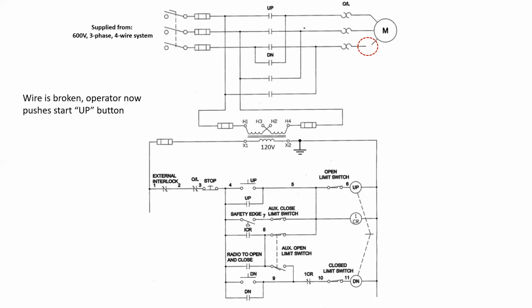So the wire's broken, and if we start the motor, it's highly likely that in this single phase condition, it will not have the torque available to get going and start. So what you might end up hearing is the motor trying to start, but due to the load on the shaft is unable to, and it will hum. It will hum and it might turn a little bit, and then the overload will trip. So kind of interesting to know.